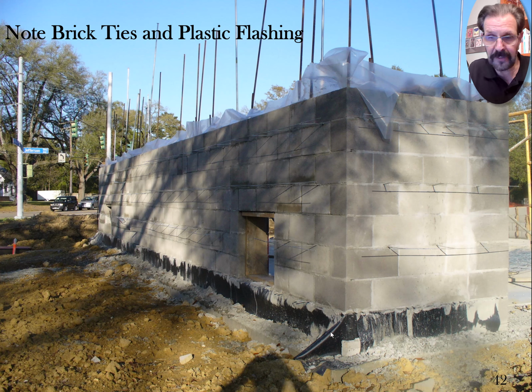The other thing you see down at the bottom is the black polyethylene sheeting. You can buy rolls of Visqueen. It's the brand name, of course, down here. That's the big brand name for plastic sheeting down here. But you can buy rolls that are only 12, 18 inches wide, already pre-cut in long rows, maybe 1,000 feet of it. And you roll this stuff in here, and you lay it into the mortar joint as you're building the wall. And then it's laying down, and it becomes this flashing, kind of an inexpensive flashing.